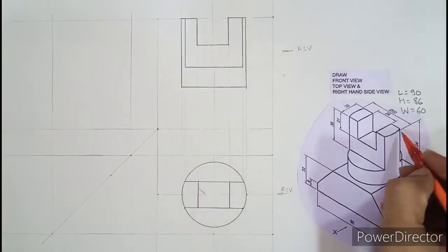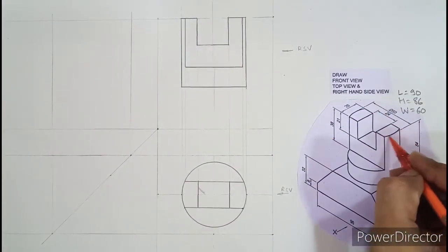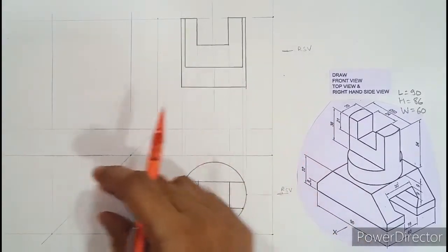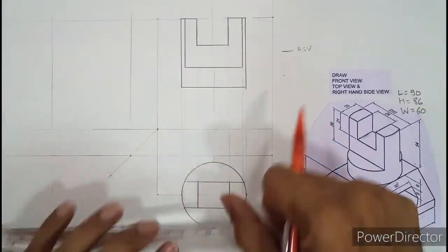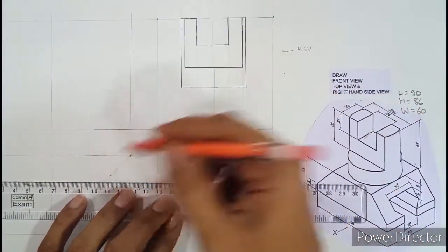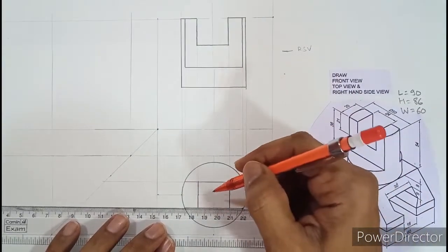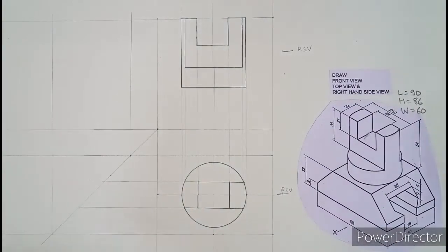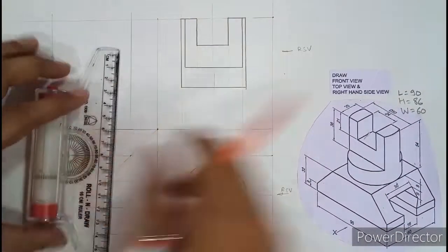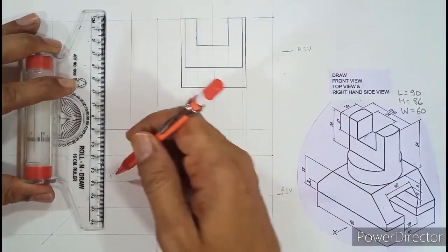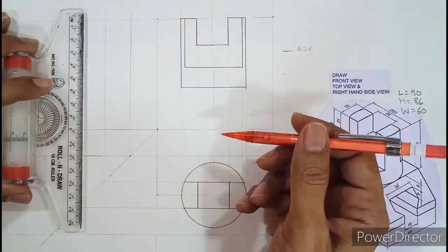So now let us start one by one. In the side view, this circular edge will be seen as a horizontal line, and that is the same as this one. So both these points, first and the second point, we need to extend till 45 and project it up. So let us do that. So from here, we need to project this and extend till here. Okay. After that, parallel to this, we need to extend this up again.